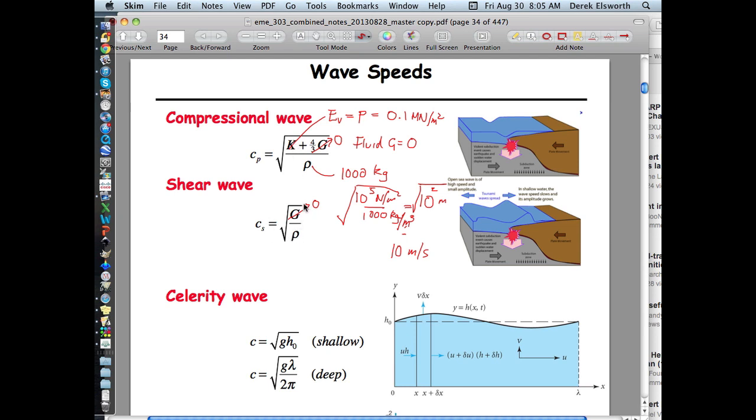So that's why, in an earthquake, you feel the initial shock first, because it's traveling at the P wave velocity, this wave velocity here, which is the sum of these two, which has to be larger than just one of these. And then the destructive wave that comes later, roughly half as fast, is the one that, if you take a skipping rope and you swing it along the ground, gives the shear motion in the ground, which actually is the thing that shakes buildings to pieces and has most of the destructive force.